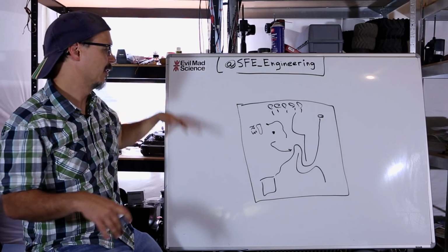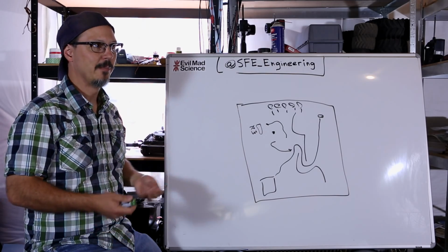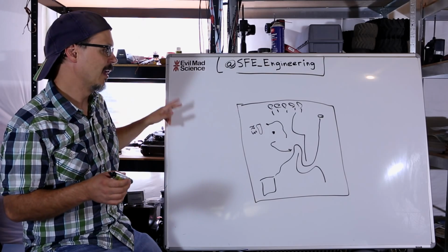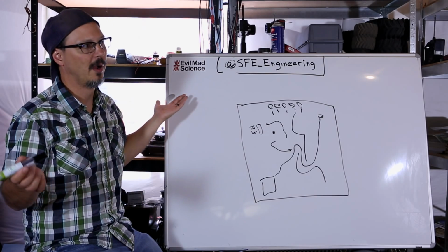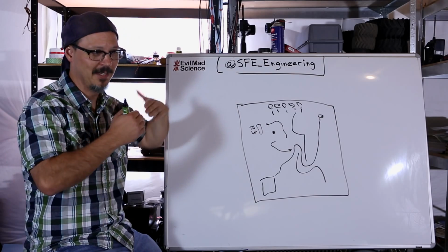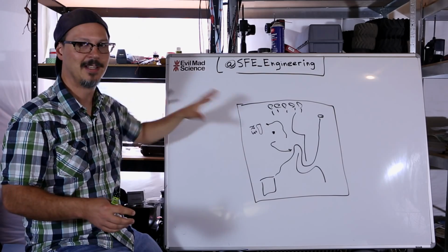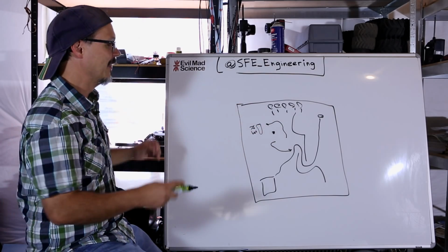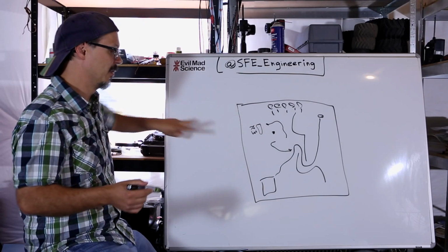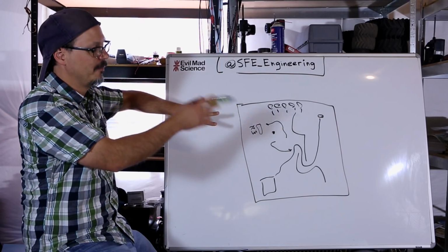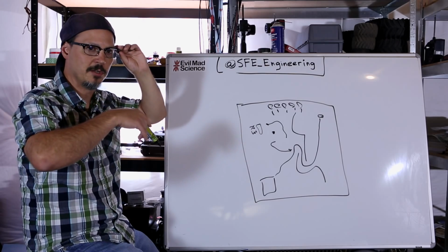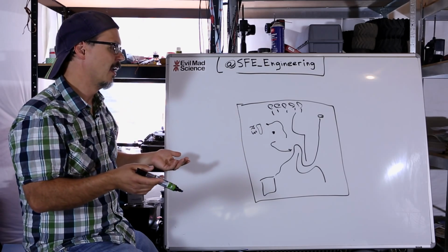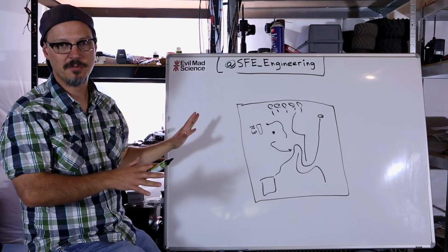So I would probably set the limit on my power supply to 100 milliamps, or 75 milliamps, something a little bit above, but not so much that anything's going to burn. Then I know that when I hook up power, if the power supply goes into a limiting situation, I've got a short and nothing has been destroyed, okay?